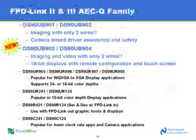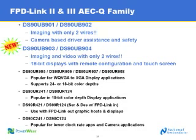So to give you the context of where these parts fit in the family of parts that we've released, the new parts now are the DS90UB 901, 902, and the 903, 904. And as we talked about, the key features of these are that they go over 2 wires for both the video and the control, and that for the 901, 902, they're targeting camera-based applications. 903, 904 is really targeting touchscreen.